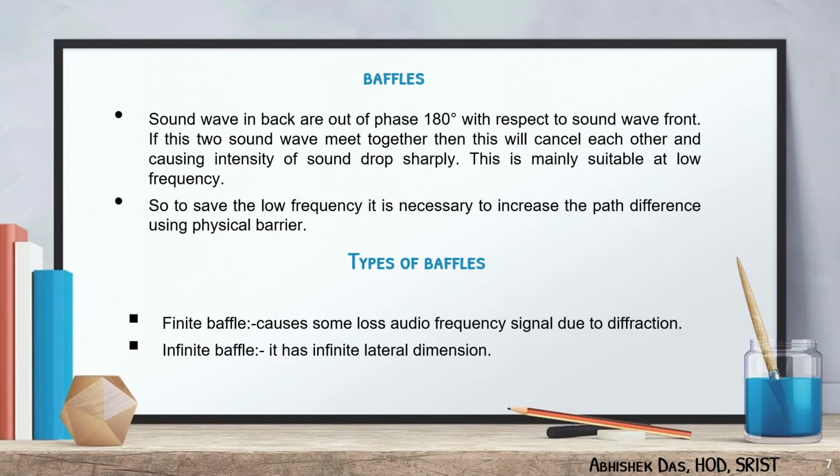Now we are discussing baffles. A baffle is a technique to recover the low frequency of sound. The sound wave from the back is out of phase by 180 degrees with respect to the sound wave from the front. If these two sound waves meet together, they will cancel each other, causing the intensity of sound to drop. This is more pronounced at low frequency.